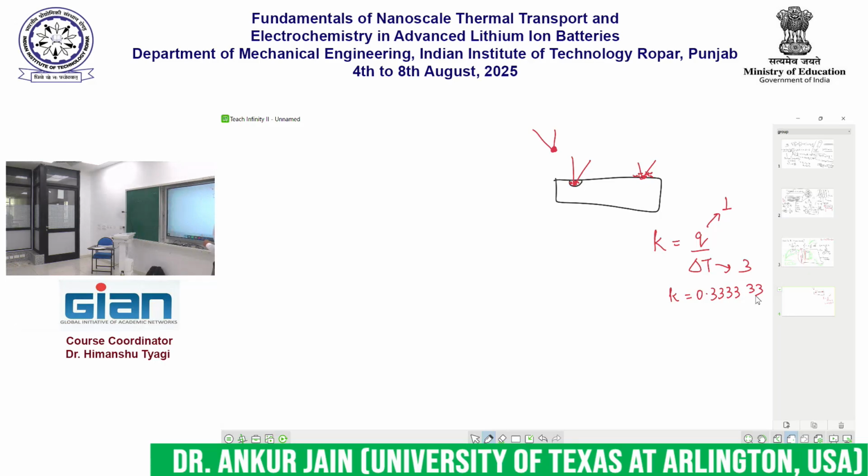Suppose for example, the measurement accuracy of this thermocouple was plus or minus 1 degrees C. What that means is that the 3 degrees C temperature that you measured could very well have been 2 or could very well have been 4, anywhere between that rather broad range. If it was actually 2, then your thermal conductivity would have ended up being 0.5, correct? If on the other hand your delta T was 4, then your thermal conductivity would end up being 0.25.